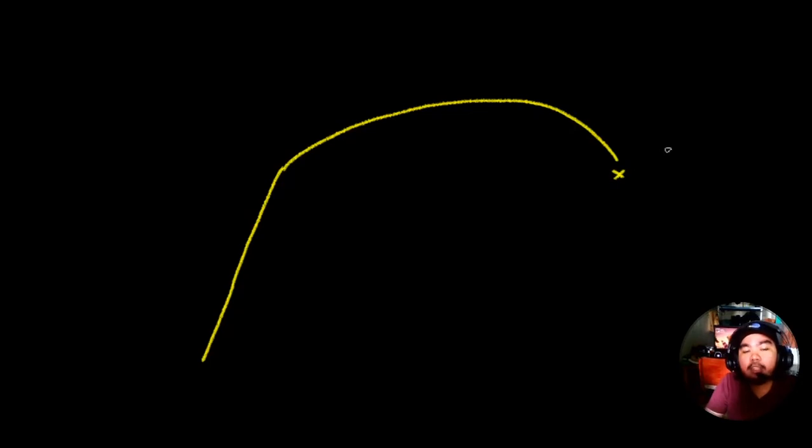So when we have, and let's draw another ideal na tensile stress strain diagram. So this is our ideal stress strain diagram na meron siyang yield point phenomenon, no? So when we try to deform our metal, so for example, ganyan, no? Then we applied load sa metal natin, then it will follow this curve, no? If it's the same material, then it will follow this curve. Then past this point, magkakaroon ka na ng plastic deformation, tama? So you get a plastic deformation hanggang dyan.